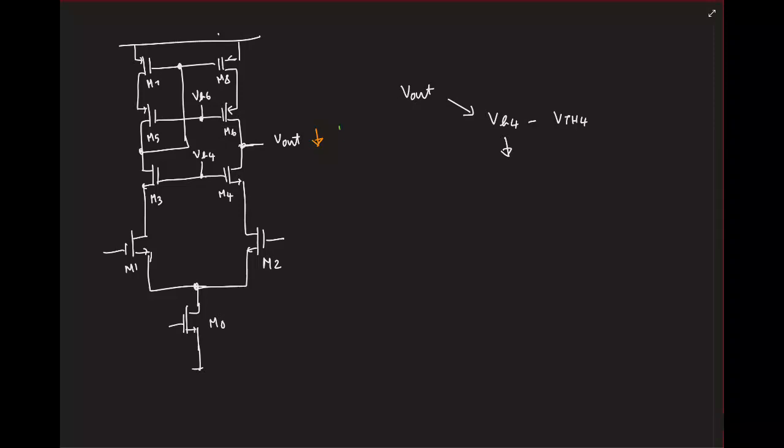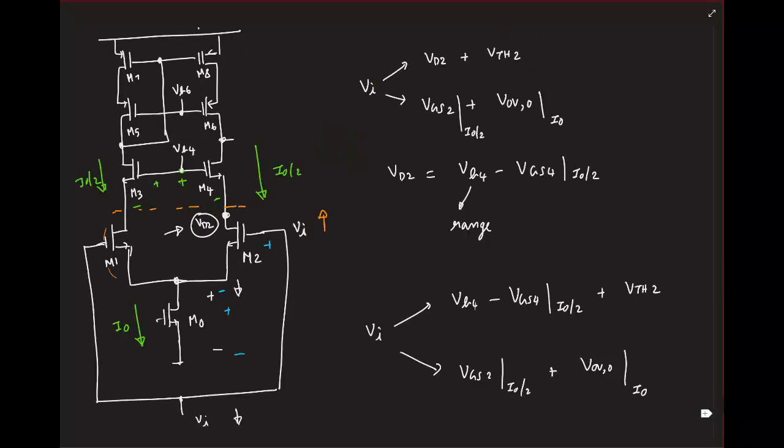Now let's do the other end. If I keep increasing Vout, which is getting affected? M6, the PMOS. So what is the maximum Vout can go without causing M6 to enter triode region? It's gate voltage plus the threshold. So gate voltage is VB6 plus, I'll just say, mod VTH of 6. Again, this guy will have its own range. Cool. So let me copy paste the input range once.